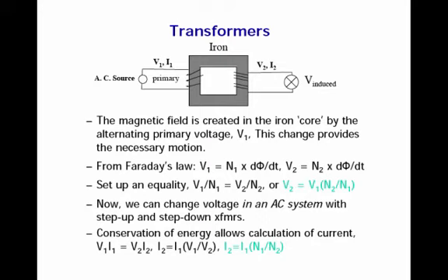So how does this work with the conservation of energy? When I step up voltage, do I step up power? Am I creating power? Am I increasing power? Of course we can't do that. So if the voltage steps up, the current must step down. So when you draw 1 amp here, you'll have to produce 2 amps over here in order to supply you with your 1 amp. So if the voltage is stepped up, N2 over N1, the current is going to be stepped down, N1 over N2.